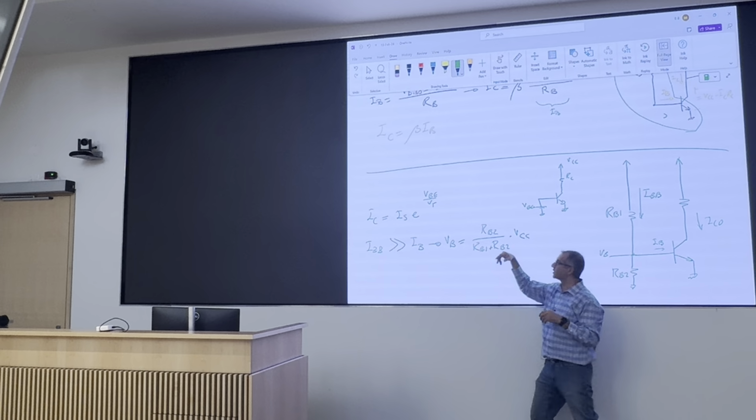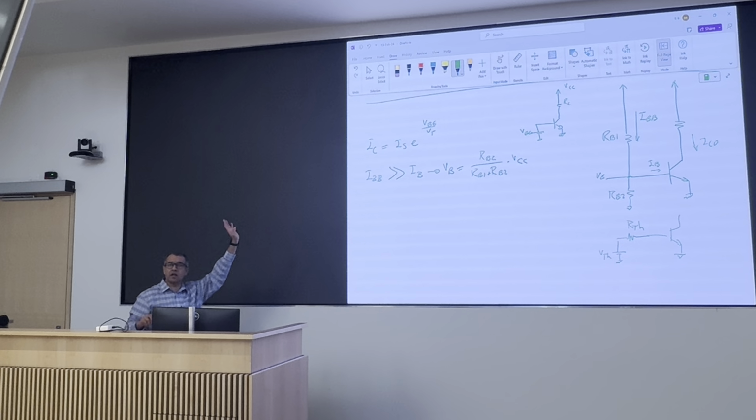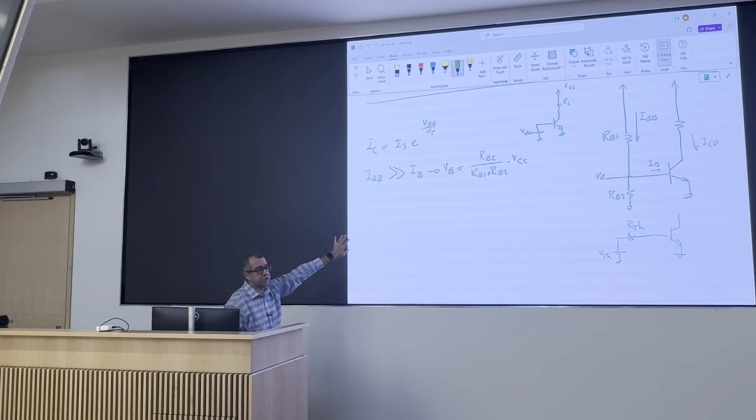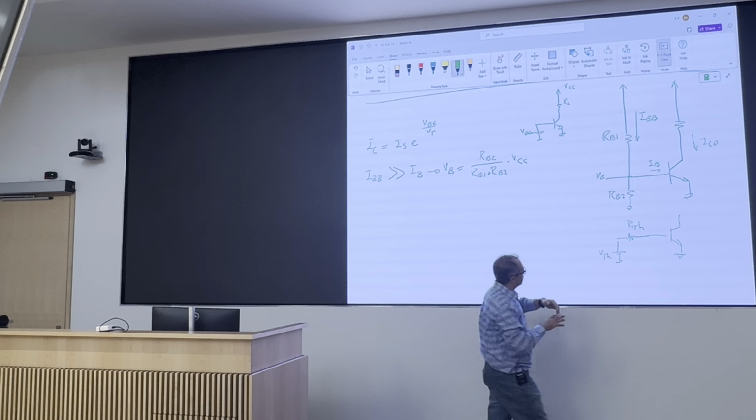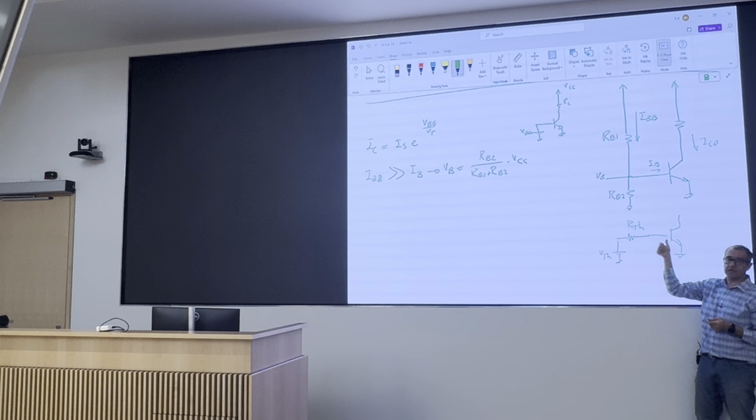So for this, I can say R Thevenin for the resistors and V Thevenin for the equivalent circuit, and then the rest is here. For the linear part, I can use Thevenin and Norton, right? Because the linear part is linear. So I can find the Thevenin and Norton equivalent of that portion of the circuit and attach it back here.